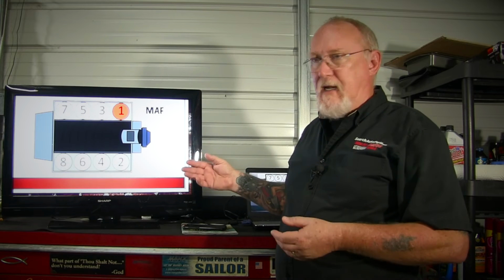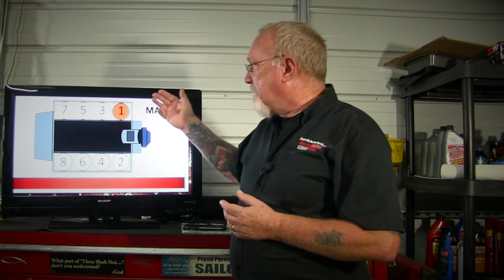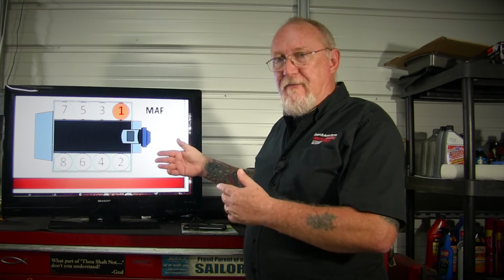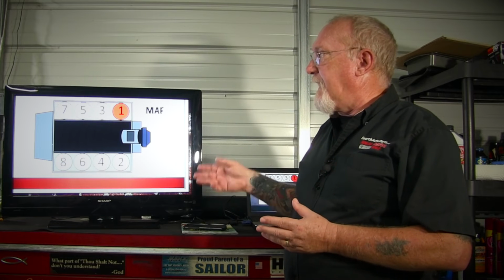Got me? So it's taking a look at the total quantity of air that came in. Let's just use a round number, 100 pounds of air. And it's going to calculate how much fuel in pounds it needs to add to the engine as a whole in order to get the proper air-fuel mixture. Well, the first thing it's going to take a look at is bank 1 and bank 2, half and half. That means if I got 100 pounds going in, each bank is getting what? 50 pounds, right? 50 pounds. So now the ECM says, okay, bank 1, I need to deliver this much fuel to, and I've got 4 injectors to do that with.